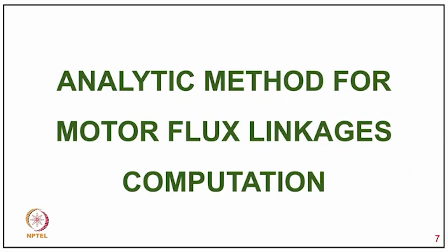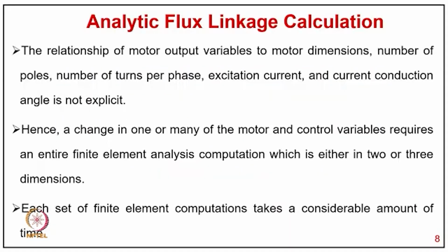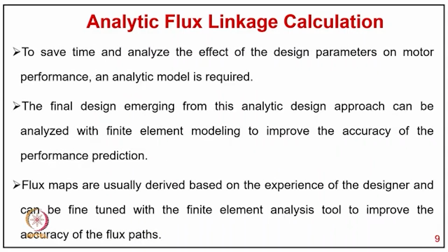So, coming to an analytical method for motor flux linkage computation. In analytical flux linkage calculation, the relationship of motor output variables to motor dimensions, number of poles, number of turns per phase, excitation current and current conduction angle is not explained. Hence, a change in one or many of the rotor and control variables requires an entire finite element analysis computation, either in 2 or 3 dimensions, and each set of finite element computation takes a considerable amount of time.